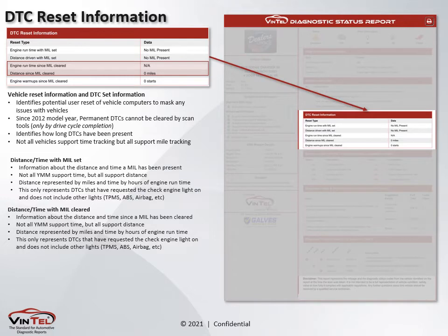One of the wonderful things about the OBD specification is its capability to self-correct or self-heal anomalies that are detected. In our example of a bad catalytic converter, let's say that you had a well-functioning catalyst and you drove through a deep puddle of water, effectively cooling the substrate within the catalytic converter and therefore rendering it below optimal performance. At that point, the computer would detect that the catalyst is no longer functioning within specifications and will set a DTC and request a MIL.